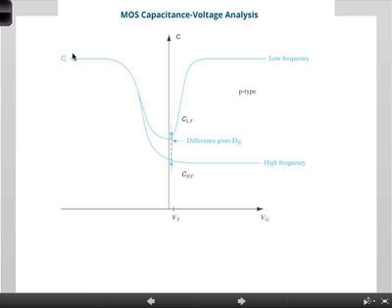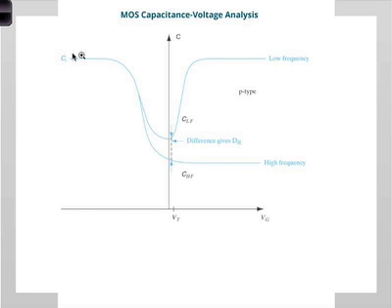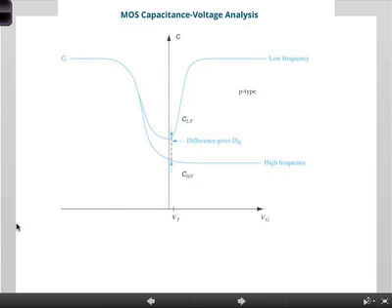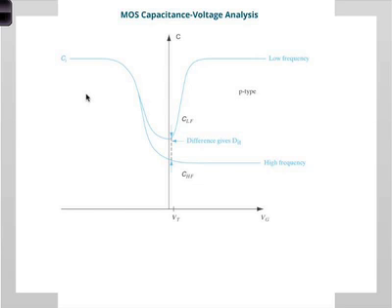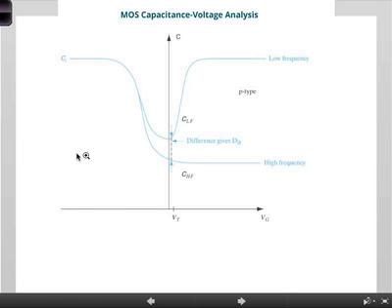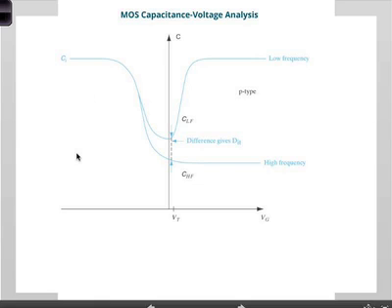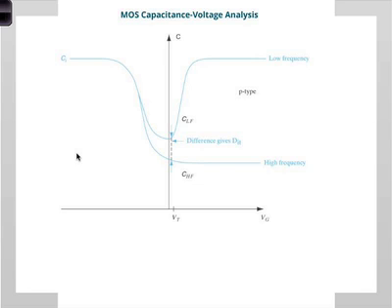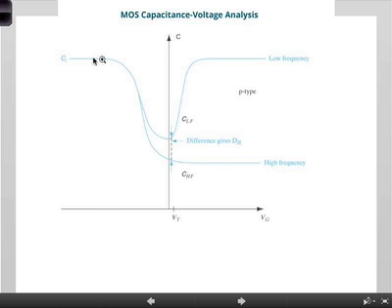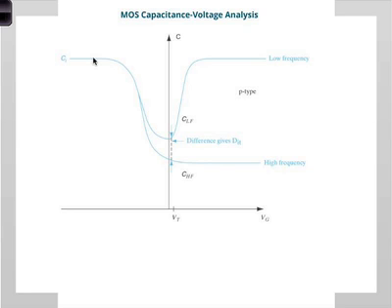Okay, out here, this is again an N-channel device, P-type substrate. Gate voltage is positive. Okay, so under normal operation, when the gate voltage is negative, it is in accumulation, right? When the gate voltage is negative, you attracted all the holes. So majority carriers are basically attracted and forming a channel, and you have no control, essentially. Okay? You really have no control on the gate, which means that the capacitance is essentially from the oxide. Okay? And it's the peak, as high as it will go.